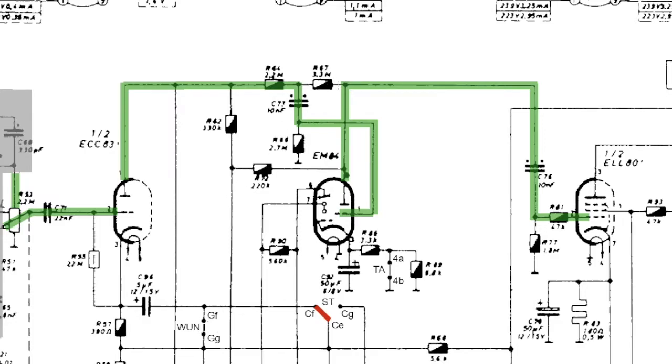This resistor here is a negative feedback resistor to that input. And the way it works is you have this signal, remember it goes down here and it gets inverted and amplified. Now if it's inverted, that signal is the reverse of that one. So if you join them, you are subtracting from it. You're giving it negative feedback. And what you want to do here is you want this stage to give you an amplification factor of -1. You just want it to invert the signal. And we'll see why we want to invert that signal. Basically, you just want to invert it.